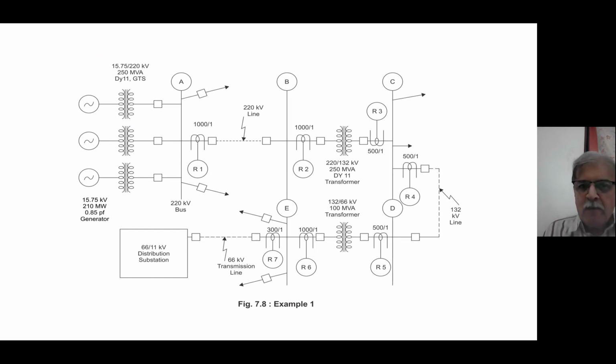That is the problem of overcurrent relays, and therefore we go to distance protection and line differential relays. But let it be on one side right now, because we cannot jump to many things at a time. It's not that there is no remedy to that. You can attach a high-set instantaneous unit to relays to make them faster.